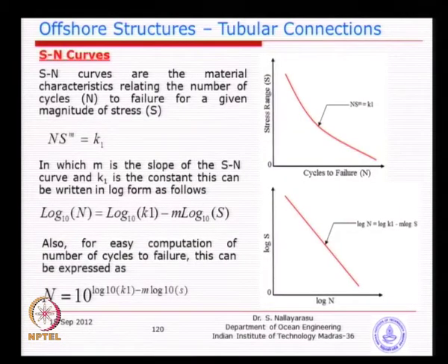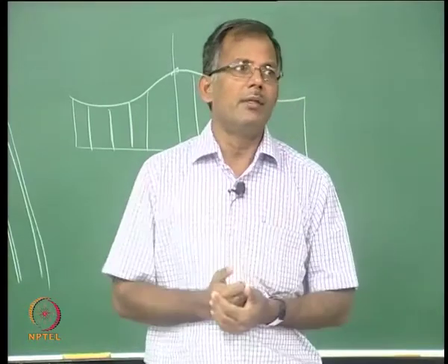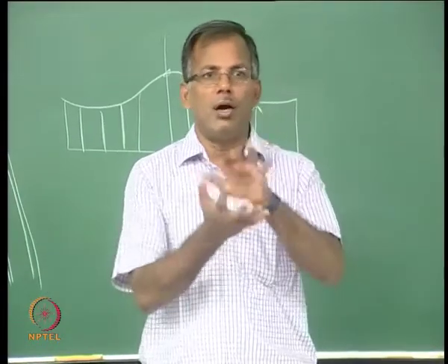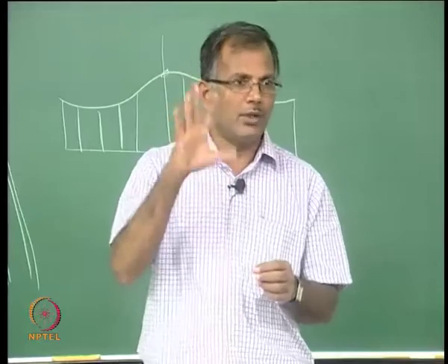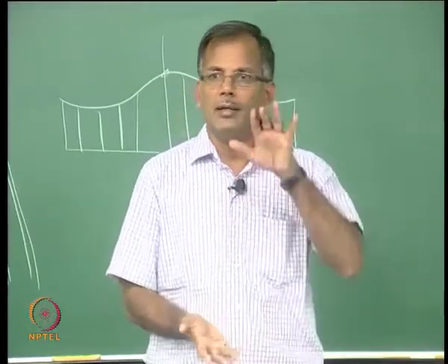The next one is basically the SN curve. What we have done is we have the nominal stress calculated from an analysis of the structure, applying a wave height and wave period, and we have calculated the stress concentration factor. Stress concentration factor multiplied by the nominal stress gives you the hotspot stress, and the stress range is defined as either twice or the difference between the maximum and minimum.